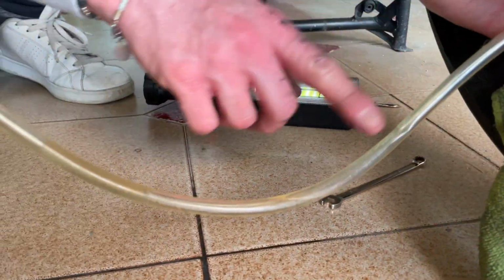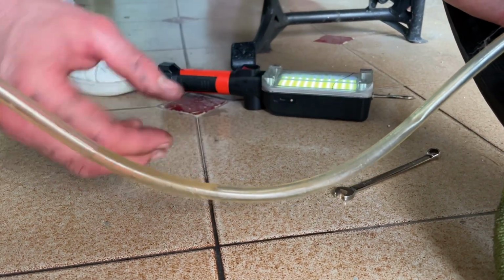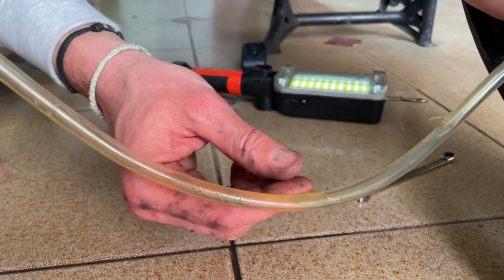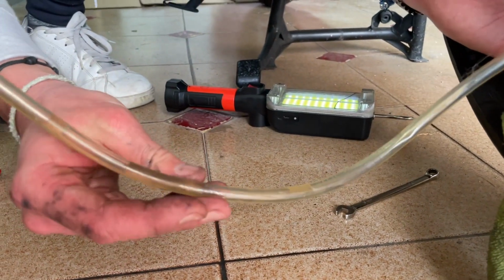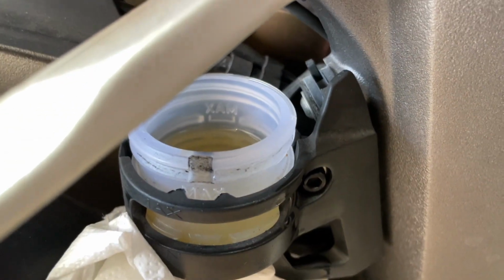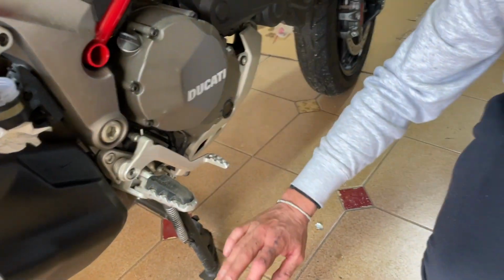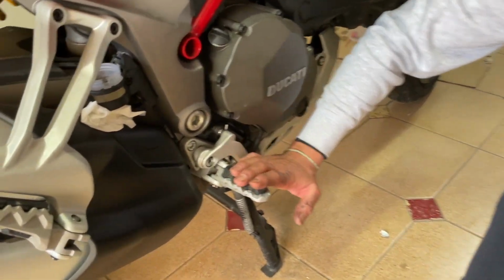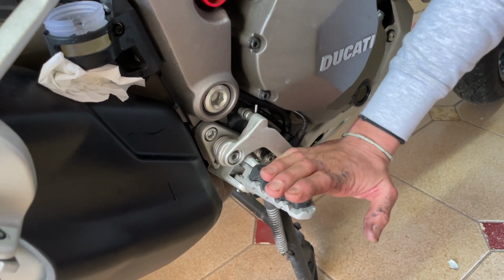As you can see, on this pipe you will not have the pipe full of oil, but if you look here, in this part, there is no bubble in the oil that is flying. So it means that hopefully now there is no more air in the circuit. But the final test is, let's have a look at the brake pedal. You remember before it was going totally down, no braking at all. Let's see now. Now it brakes. Rear brake now fixed.